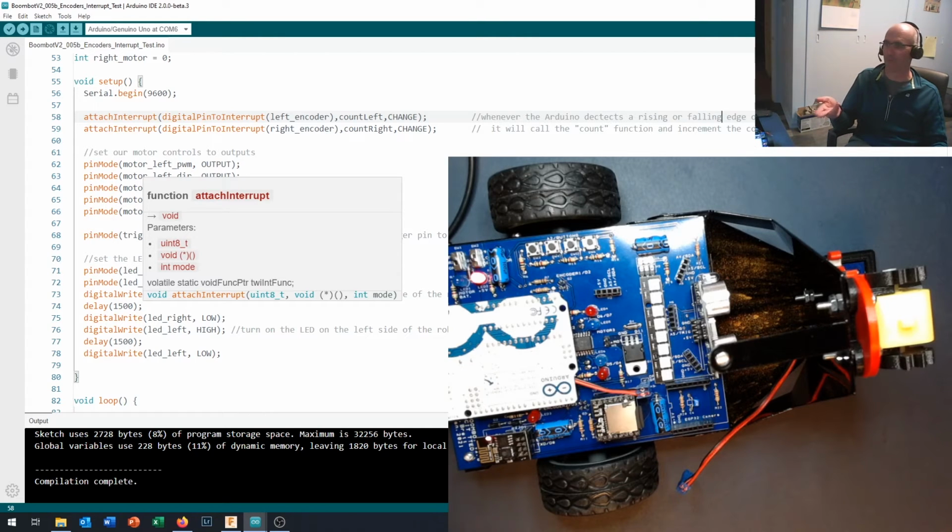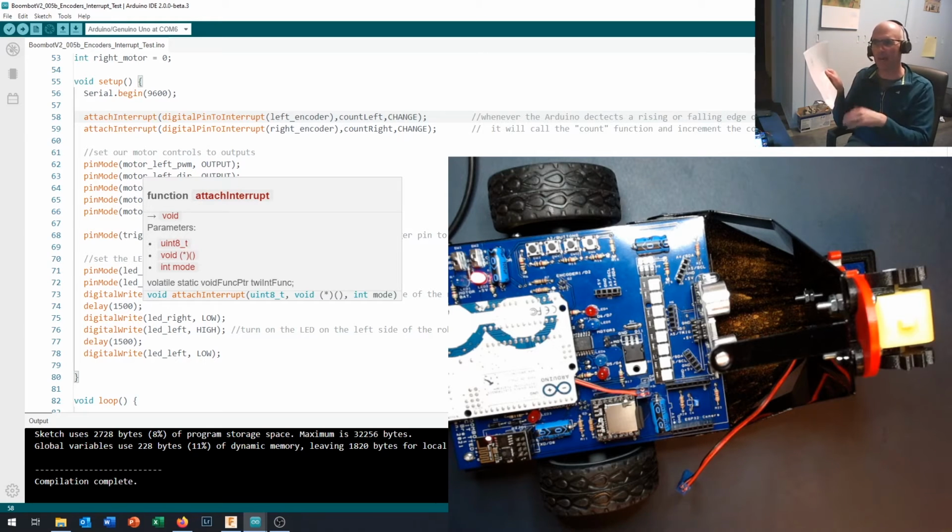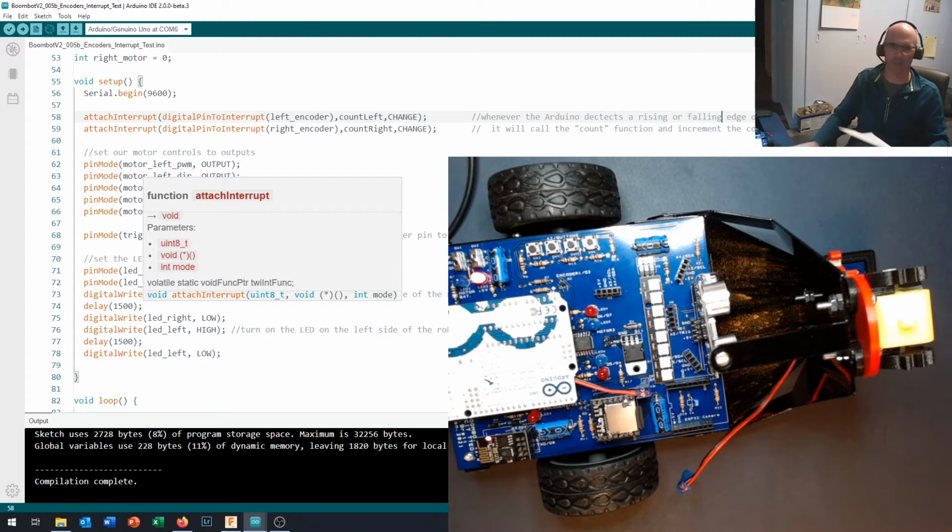So you can handle the interrupt really easily sometimes. Interrupt service routines need to be handled quickly, okay? Because you've got your main program right here and you've got all your material that you need to get out to the students. And if the interrupt service routine goes on too long, you've interrupted the main code and you've caused a problem. So you need to have really, really quick and efficient interrupt service routines.